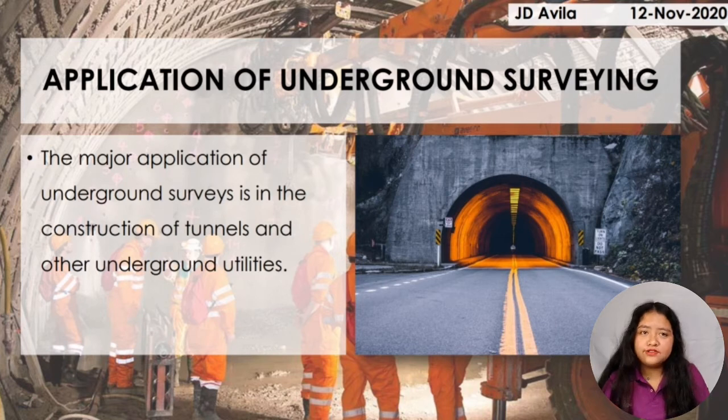A tunnel is constructed when open excavation becomes uneconomical, usually when it is more than 20 meters. It reduces the grade and shortens the distance between given points separated by a dividing mountain or a ridge. Underground surveying meets the demand of modern rapid transit in the city. We can also have exact alignment, proper gradient, and establishment of permanent stations marking the proposed route.